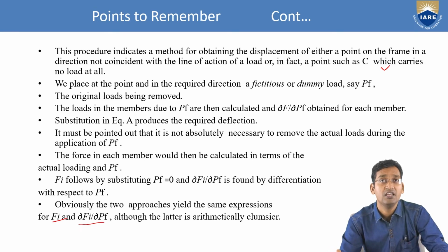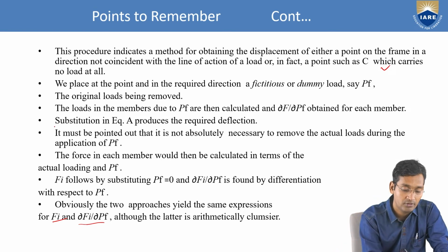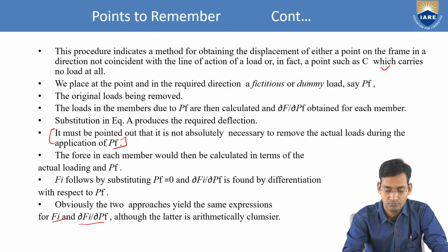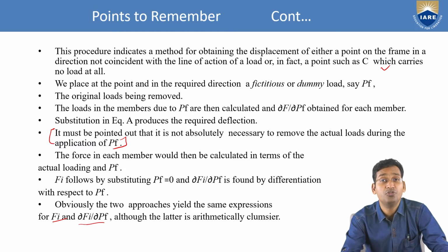Okay, next, it must be pointed out that it is not absolutely necessary to remove the actual load during the application of PF. So just take care of this line, right? It is not necessary to remove the actual load. Without removing the actual load also we can find it. The forces in each member would then be calculated in terms of actual loading and PF.